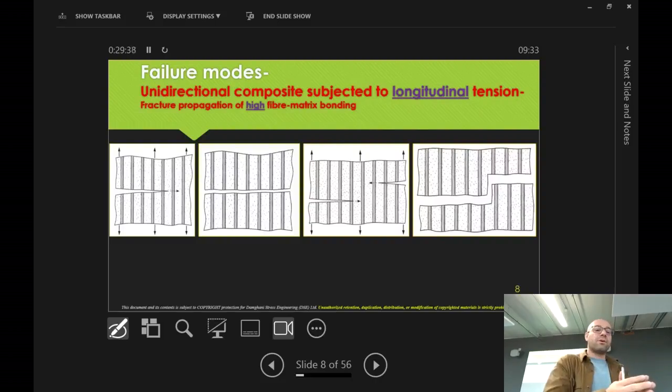Often that's the case for renewables and the aerospace industry. And the other way that we do at UV is hot pressing. We've got a hot press, we just press it down at a certain temperature, 100 psi. But with hot pressing, you can't create complex shapes, just flat shapes. You can't really create anything else. But with autoclave, you can make very complex concave shapes.